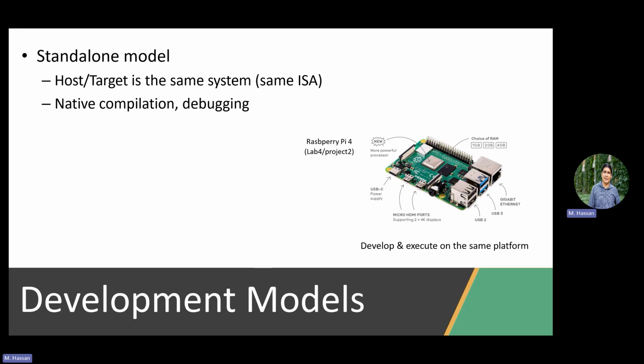Programs really need to be optimized. I cannot have a million lines of code in an embedded system. Excellent. To do the same task, but with much fewer lines of code. Yeah, excellent. And the reason for this is memory space. Yeah, memory space, usually resource constrained, right? So we call embedded systems resource constrained devices compared to your laptop or desktop. So you have to be aware of the resources, right? And we will see some of the implications: how you pick your data types, how you define your memory behavior, that stuff, right? So that's one of the things to keep in mind, which is the most important one, by the way.